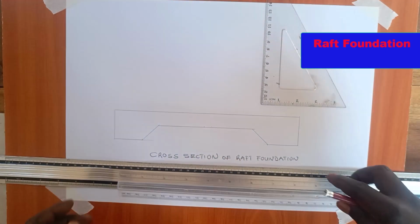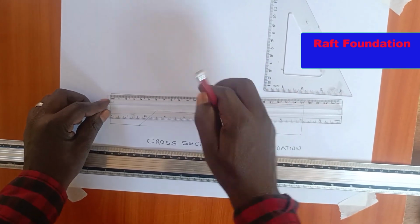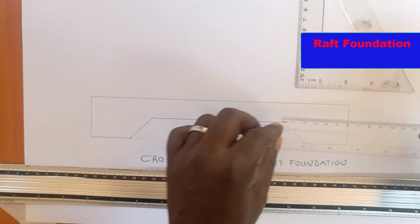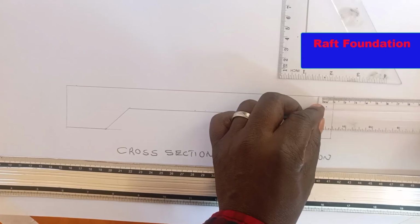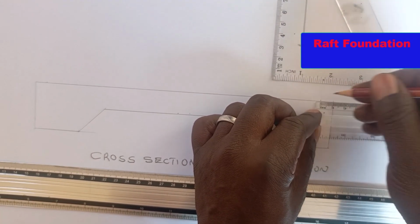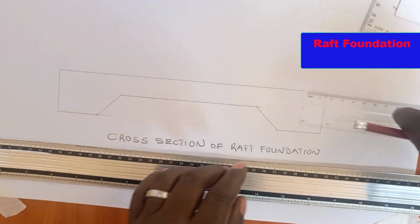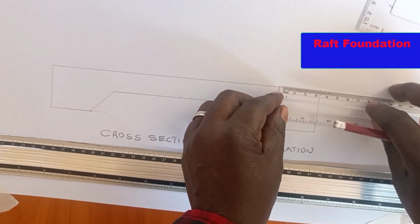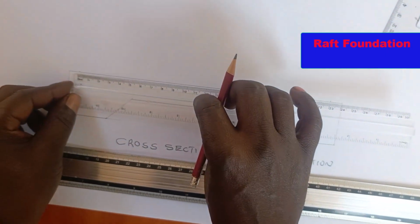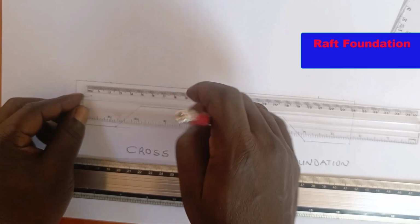So I can measure this one here at 100 millimeter. Then I make my external wall 100 millimeter here. I mark also this side 100 millimeter. Yes. So I measure the thickness of the wall, which is going to be 230 millimeter. I marked here the thickness of the wall, 230 millimeter. I marked here.